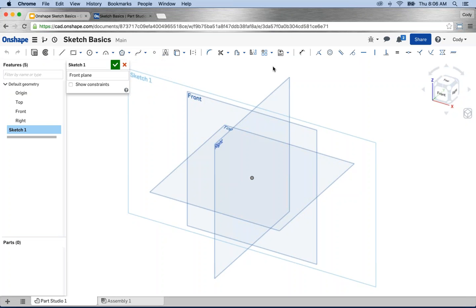And to rotate that to what we refer to often as normal to the sketch plane, you can do it most commonly with the right click. Now, there's a few things that I'd recommend when you're first getting started. One of the biggest tips for the new user is the right click menu. It has context sensitive options. So if I'm in a sketch, I get exit sketch or copy. Or view normal to the sketch plane. So very important functions in the right click.